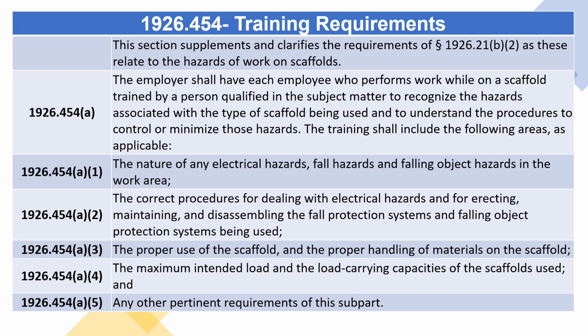The nature of any electrical hazards, fall hazards, and falling object hazards in the work area. The correct procedures for dealing with electrical hazards and for erecting, maintaining, and disassembling the fall protection systems and falling object protection systems being used. The proper use of the scaffold, and the proper handling of materials on the scaffold. The maximum intended load and the load-carrying capacities of the scaffolds used, and any other pertinent requirements of this subpart.